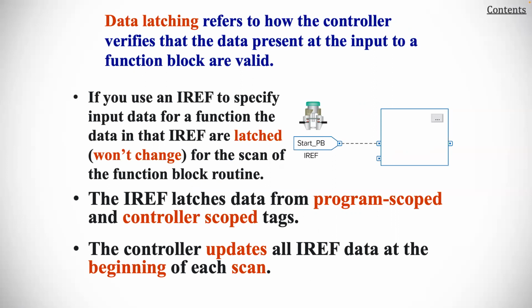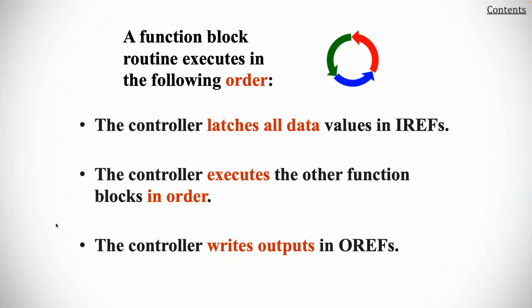That data in that IREF or latch for the scan of the function block routine. The IREF latches data from program scoped and controller scoped tags. The controller updates all IREF data at the beginning of each scan. A function block routine executes in the following order.